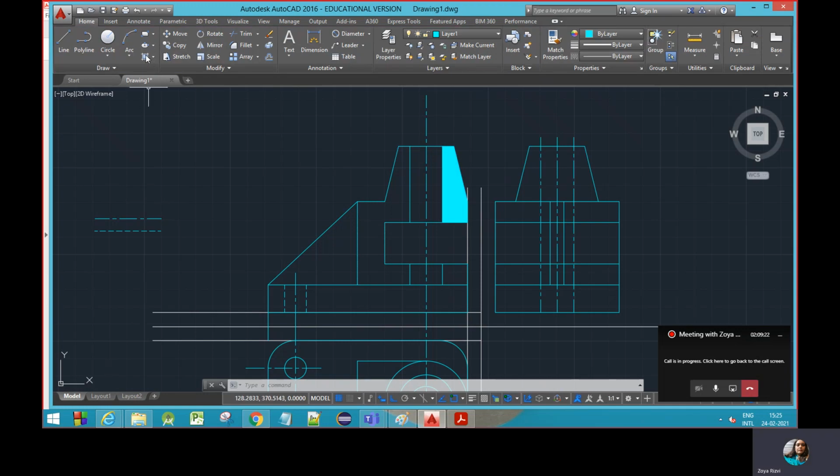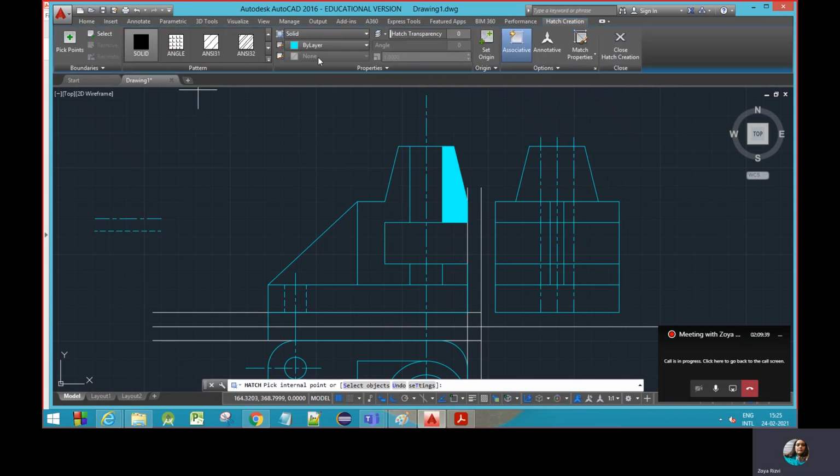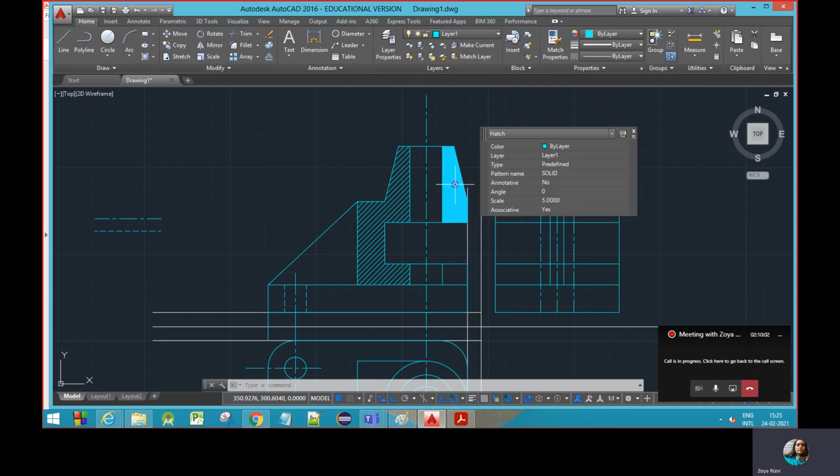The hatching lines are very dense in this. The hatch command is not responding right now. So I will fill it like this, but on your side it should not be like this. It should be a command in which you can specify its scale. Okay, if I select this, now it is highlighted, so I can make it 110. Say enter, and then if I go in, it's better now, so I can make it 20. I think 20 is a much better denseness.